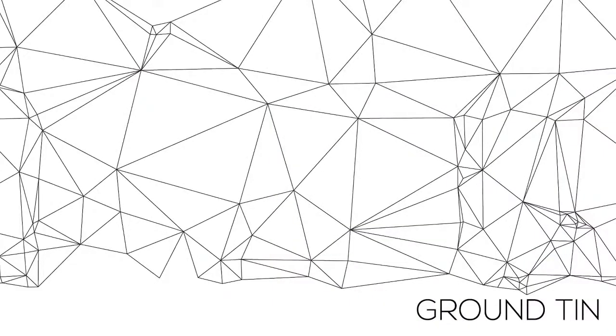Thank you, Marit. Our main input is a digital terrain model consisting of a triangle irregular network, also called a tin. Each 2D vertex has a height value and can therefore be lifted up to that height. As there can be only one vertex on a unique 2D location, vertical surfaces cannot exist. This is so-called 2.5D.